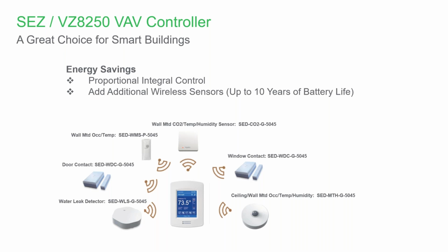So you can see the communication status, the battery status, and the actual values that are being reported by it as individual points. So if I look at a motion sensor, it has occupancy and temperature, then it has battery status and communication status. So those 4 BACnet objects for each one of those occupancy sensors that you can alarm off of and put them on graphics and do whatever you want. So hopefully that answers the question. So standalone, you can walk up to it and see it. And if it's on a network, then you can see them all on your front end. Okay. Thanks, David. Yep. Floyd, thanks. You're very welcome.